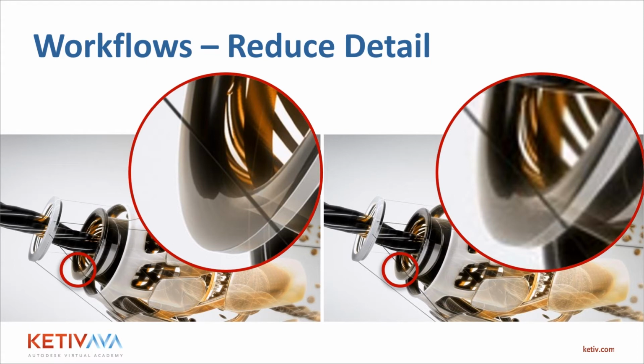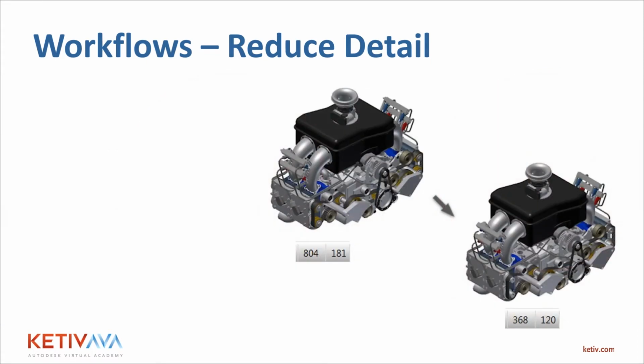So this is how this works, right? We reduce detail in our assembly. So again, you see an assembly there. They both look identical, but I'm sure if you were to dig through this a little bit closer, maybe even do a cross section, you would notice some things, some details are missing. You obviously still want a bill of materials, right, that reflects the right components. You want the drawings to look correct. At this point, this is enough detail to communicate that with this model.